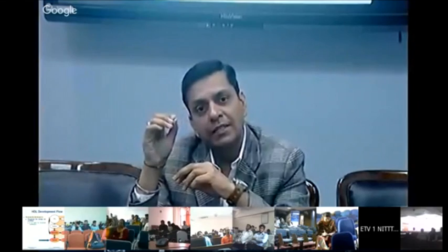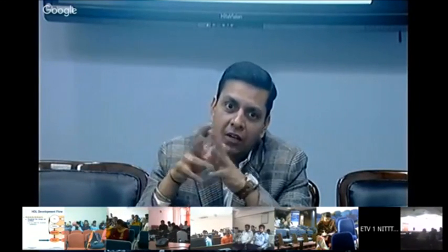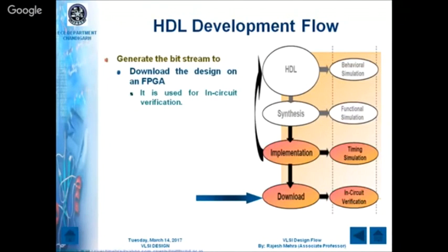Each bit is basically related with different programmable interconnects. In order to make your circuit on that particular chip, you have to program some bits, and if you want to program some bits, you have to make them 1. So wherever you need programming, all those bits will become 1 and the rest will remain 0. Initially when you start with a PLD, all the bits will be 0. It means your chip is not programmed.